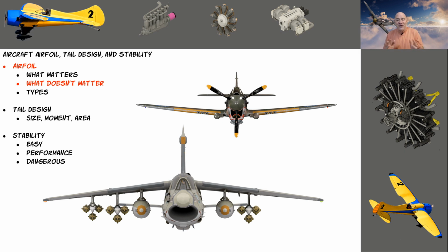So most airfoils that you pick for your airplane are going to work, okay? And there's only five or six that I ever use, and I'm going to show those to you in a minute. So let's dive into it because, look, I'm really passionate about making this super easy, especially if you're a newbie. I mean, there are styrofoam planes flying that don't even have an airfoil, and they fly decent, okay? I'll never forget when I got some of the flat foam type airplanes that didn't have airfoils, I flew them with little electric motors in my house. They flew pretty daggone good. Now they won't go quick because they'll flutter because there's not an airfoil there, but they flew.